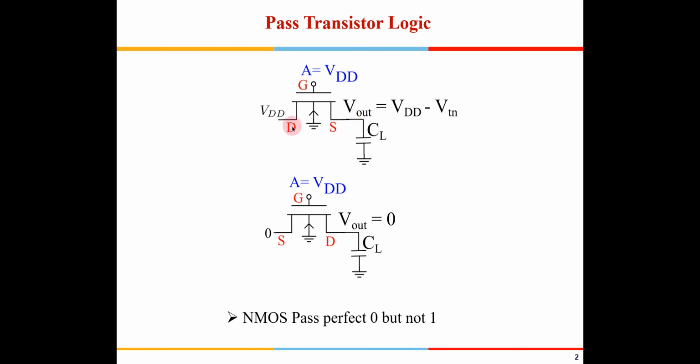Now if you remember, why do we call this the drain and this the source, and not call this the source and assume that this will be switched on? Because this is an NMOS out here. The positive charges will flow from drain to source, and the electrons will flow from the source to drain. Since the flow of the electrons is from right to left, we call this right terminal the source in this particular configuration.